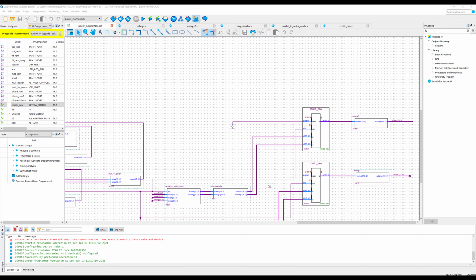So really the strategy now is these 20 bits out of the CORDIC, we will leave those in fixed point, and we will do the conversion in Matlab. It's just much easier, and it's quite a simple conversion anyway. So at the moment, let's just accept the fact that these 20 bits will be in fixed point. We will append a string of zeros to make it 32 bits, and we will do the conversion back down to those 20 bits and convert it back to decimal in Matlab. So that's good enough for now, but what's next in this design?